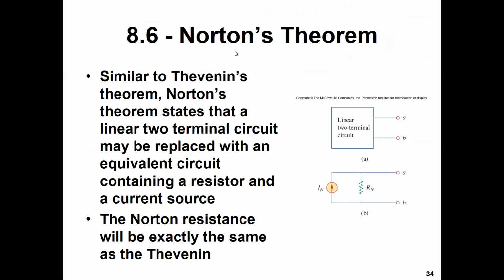Now Norton's theorem is very similar to Thevenin's. If you are given Thevenin, you will be able to find the Norton. So IN will be VTH over RTH.